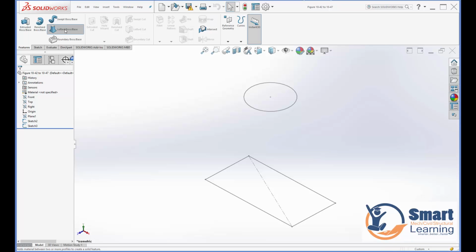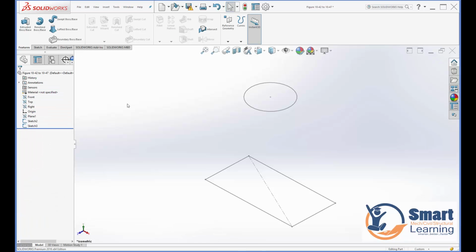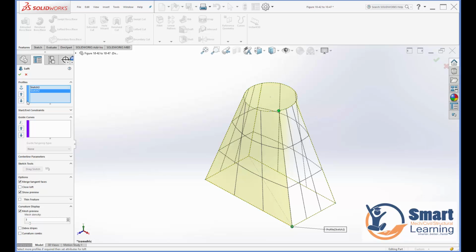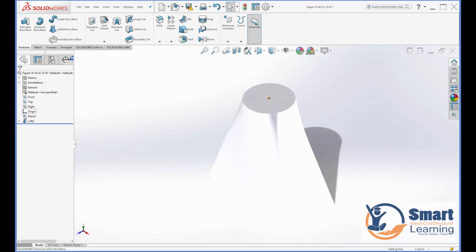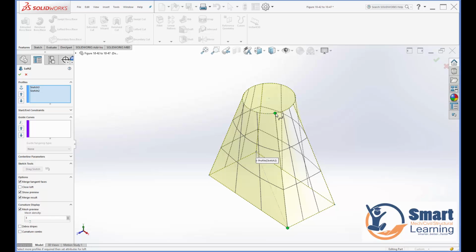So here is the loft, and here you can see the profile, and here you can see the guides, and how to do that is very, very important to follow step by step. So what you need to do is go to this particular loft feature, and here you have the profile, you can select your profile, and you can select your second profile too. And based on that, you can see this is your preview, and the loft feature is built, and you can create this. But I want to show you some advanced features where you can see this particular green start button here and here.